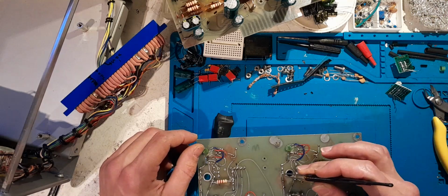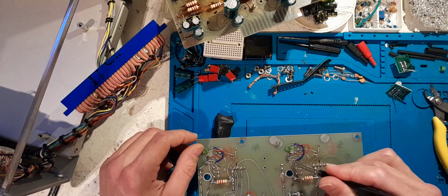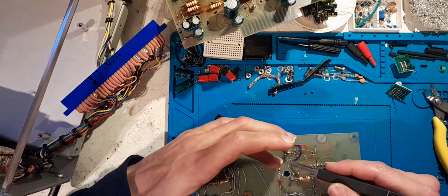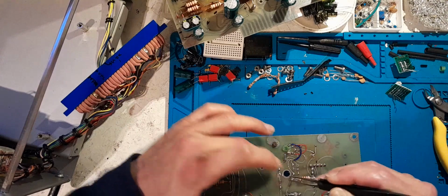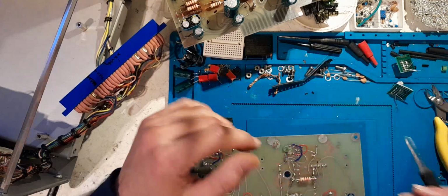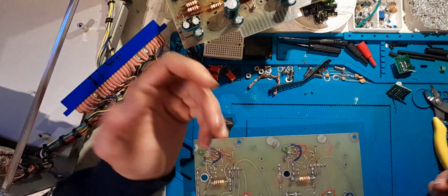And that leaves me still all this space here to add capacitors to it, leading up to the input of the op-amp, which you want the capacitors in between the input of the op-amp and the reference, not before the reference or on long wires away from the reference, you know what I mean? So that kind of just works out perfectly.